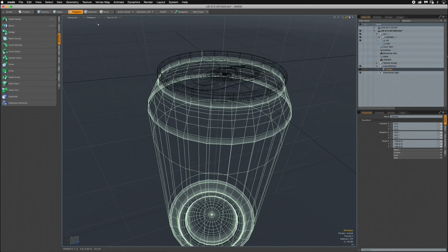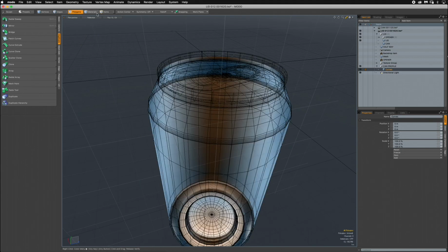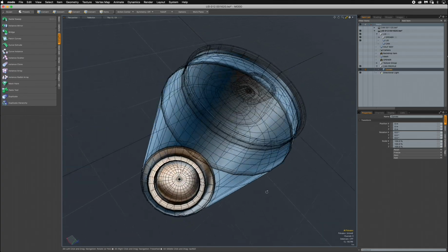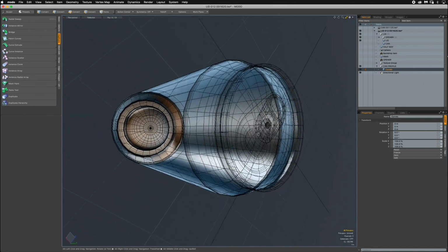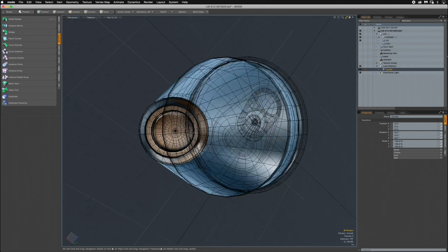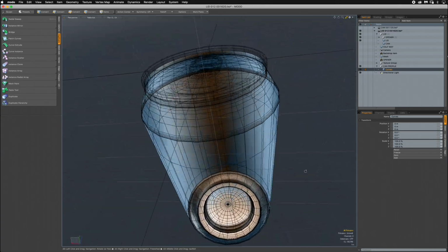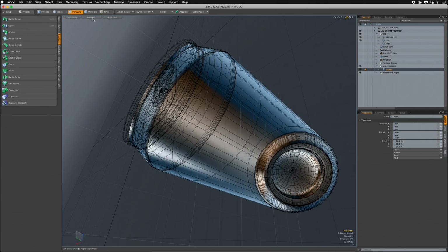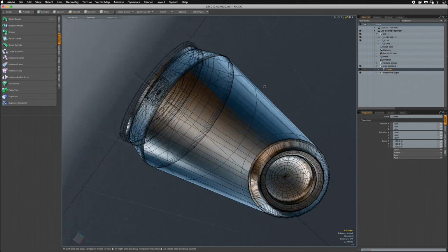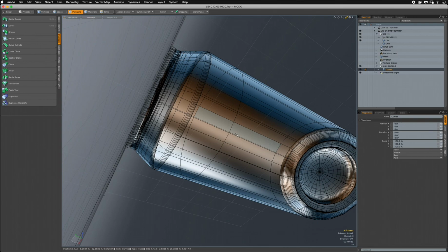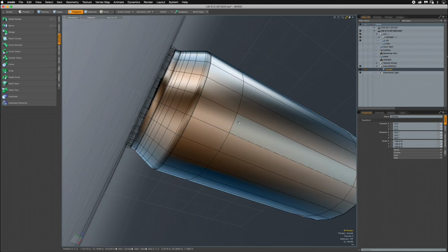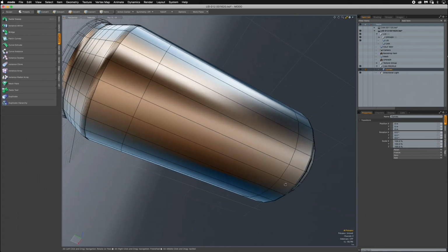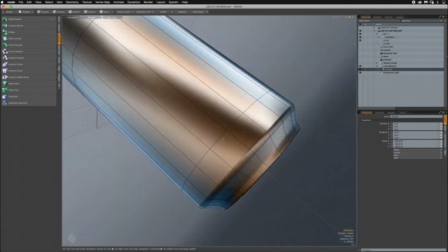So now, it looks like the polygons are inverse on mine. It might not be on yours. Sometimes things like this happen. So if it looks kind of ghosted, when you select reflection and it doesn't look solid, it looks like it's inverse, just press F on your keyboard. Just click F and it'll flip the polygons. It's just the polygons were flipped.